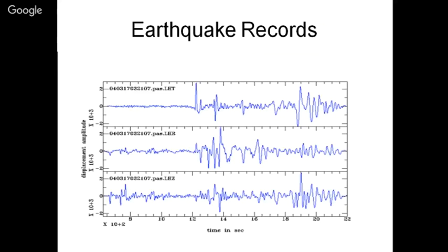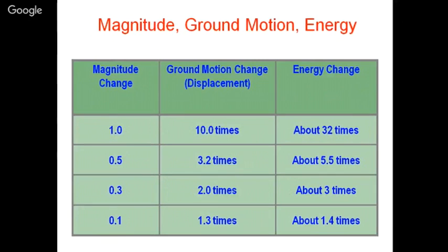These are typical earthquake records, which are recorded in an accelerogram. As soon as an earthquake comes, a needle moves on a paper which is being rolled. I can show you in my succeeding slides. This is the type of record which is recorded, and in this we make the difference between the P wave and the S wave, which comes initially and later, and from that we find out the coda length and then the magnitude.